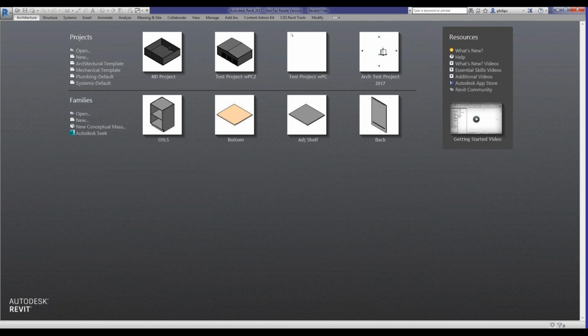One thing that I do suggest is when you are creating some Revit content to think about which product release that you want to be creating them in, because when you start those projects, you know that they always have to stay within the same release. So architecture, MEP, structure, if you're working with different companies on a project, they all have to stay within that same release number. So if it's a 2016 project, make sure you're developing your families in a 2016 or maybe even back to a 2015 version.